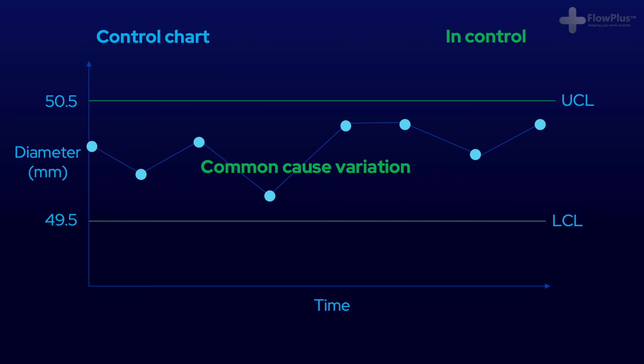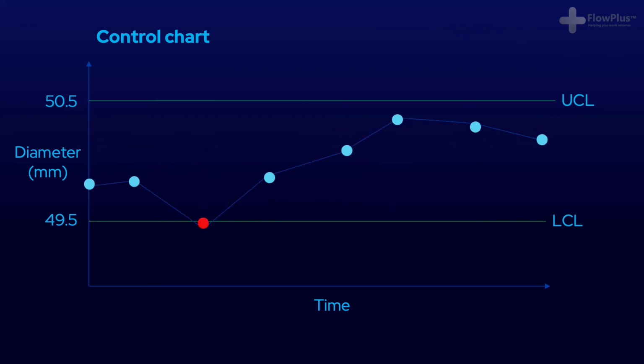We'll not go into detail too much about how these control limits have been calculated, but they are based on the outputs of the process over time, and they're calculated mathematically so that anything outside of them statistically shows that there could be a problem. When a process is in control like this, it is predictable, and we know the process is performing within its limits. Now if we look at another example of the process, this is out of control.